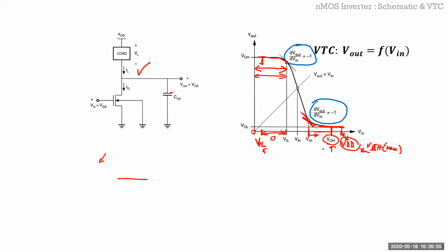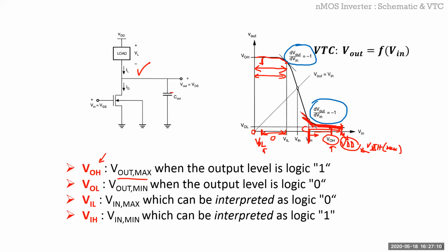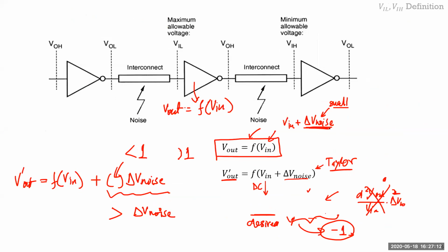In this range, you forget it, and same thing at the output here. The output is still low, and you keep decreasing it till this point where the gain starts increasing, and you say, I'll just stop here, and that's your noise margin high. So that's both your graphical and mathematical way of describing why you're choosing that derivative to be -1 to define your VIH and VIL.